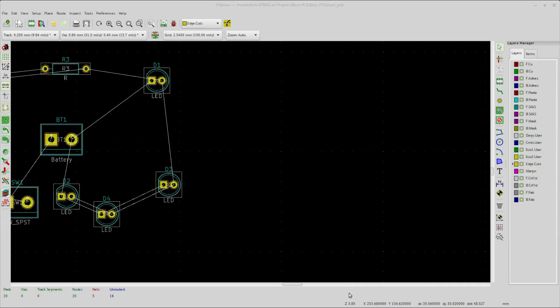If you look right down here, you will find your absolute coordinates, so your XY position, that's not going to change. Over here, this is going to be based upon the origin of your choosing. So, for example, if I were to just move this around anywhere, you see how it doesn't snap to anything? If I hit spacebar, watch down here, it zeroes that out, and now as I move it around, the XY is relative to that position. The reason it didn't make sense is because there was no dot to snap to right there.